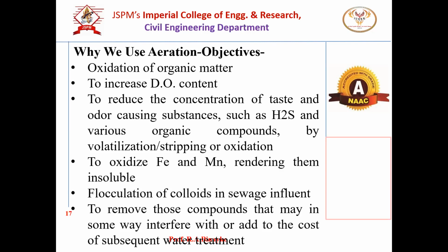Second, to increase the dissolved oxygen content, as I told you previously. Third, to reduce the concentration of taste and objectionable odor, meaning very bad smell, such as the bad odor caused by hydrogen sulfide gas. That is reduced by the addition of oxygen, by volatilization, stripping, or whatever process we are carrying out.